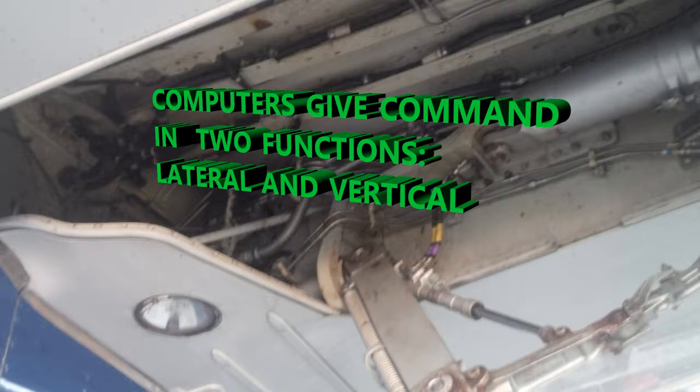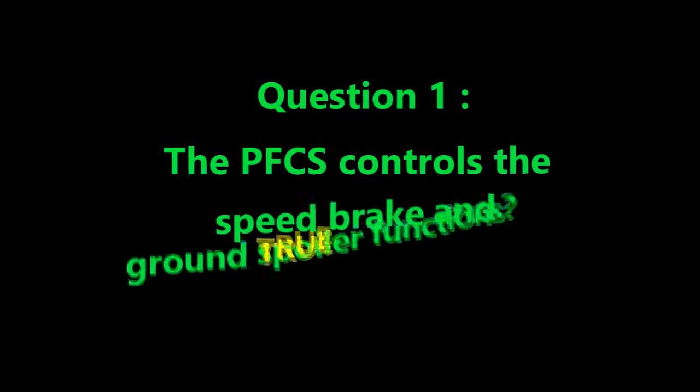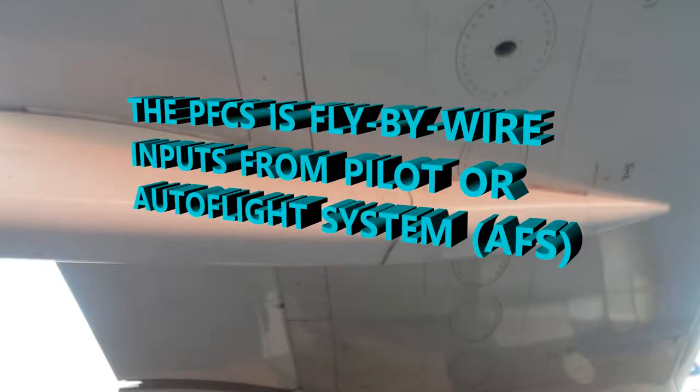Now, we know that the primary flight control system is a fly-by-wire setup, which simply means that you have computers getting the sensor inputs from various sources, not just from the manual input from the pilot, for example your side sticks, but also from your ailerons and your accelerometers, your remote gyro and accelerometer units.